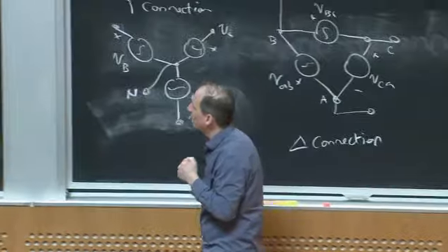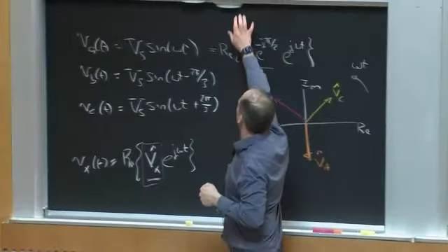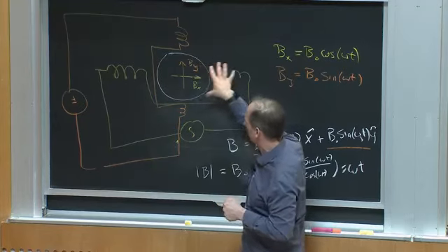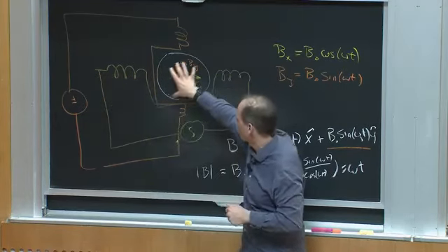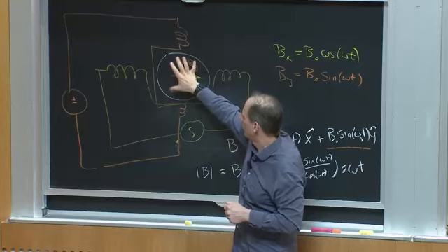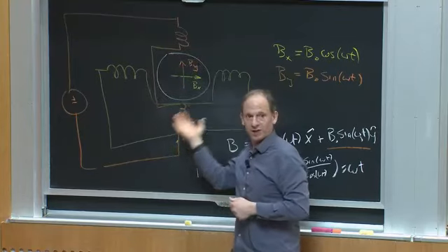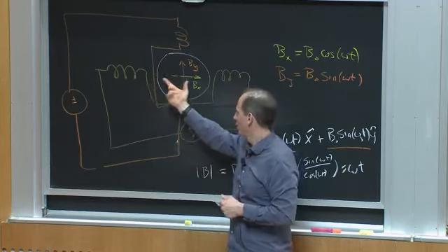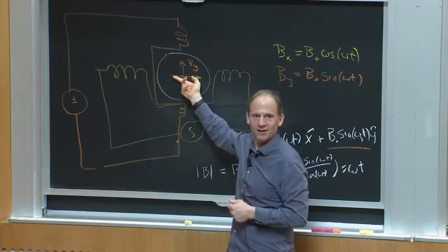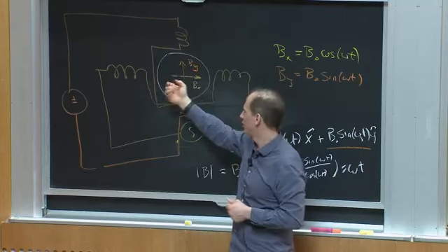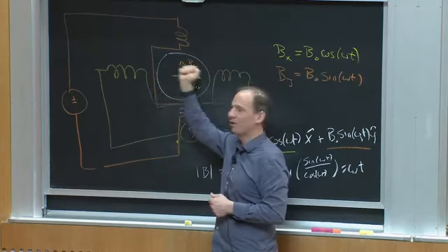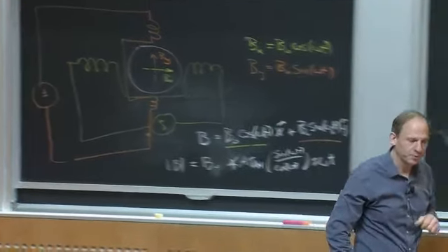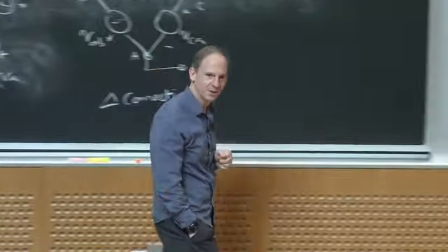I've already shown you one, actually, and that is that because I can create a rotating magnetic field, if I only had a single phase and I started misaligned with my rotor, I could get it going and it would spin. I can transfer energy that way. But if I started out aligned, it just would never start. It would just sit there, because with single phase I can only generate one physical direction, whereas with polyphase, I can generate multiple directions. So that's one reason. That's a 0th reason I might do it.